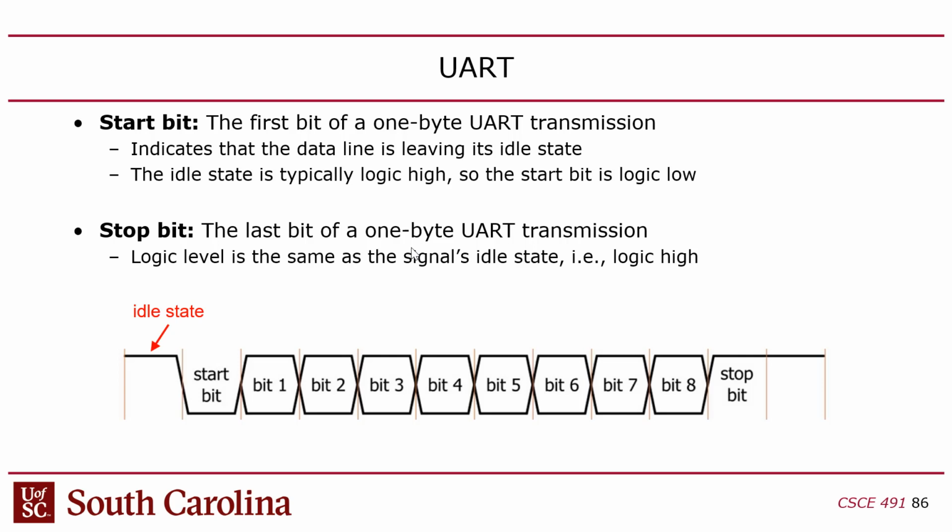The other problem is that even if you match speeds, there's no guarantee that the receiver is not going to try to read while the driver is transitioning the bit. There's no guarantee that you won't go into metastability on the capture register on the receiving side. Now, the thinking behind this by the UART people is that yes, there's no guarantee, and you will get bit errors.